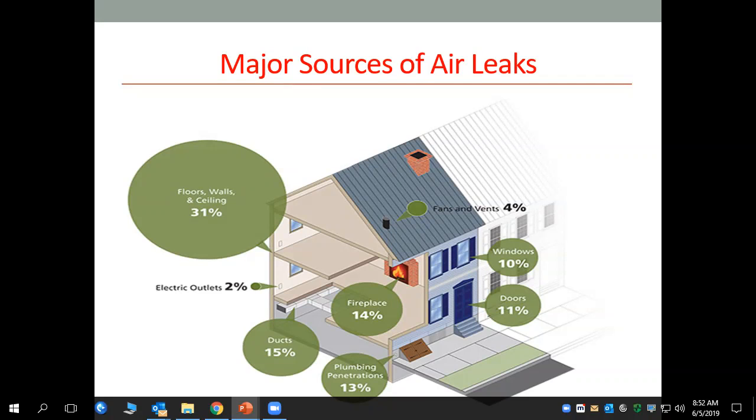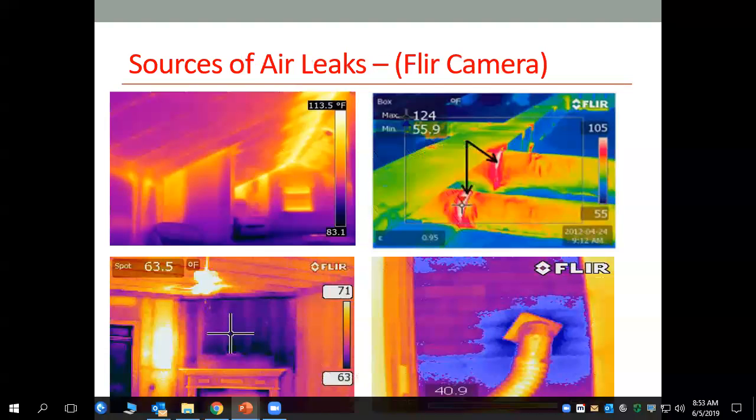Every time you make a hole, you create an opportunity for leakage. Then you have doors. Doors are inherently leaky just from the fact of door sweeps and how their framing is gasketed to seal up, and then windows, same thing. There are a lot of manufacturers, and the way that windows are installed, they get a lot of blame for things, and in many cases it's the installation and not the product itself. And then you've got the electrical outlets that aren't sealed well that can have leakage.